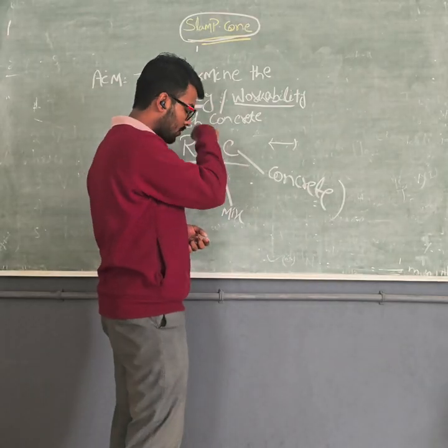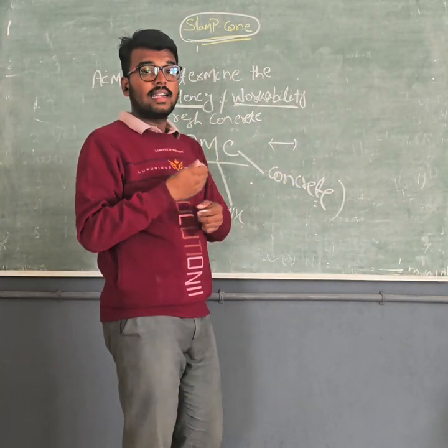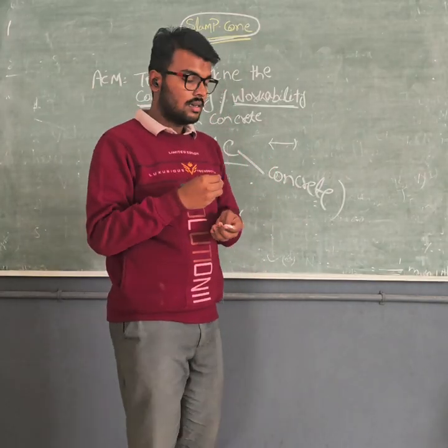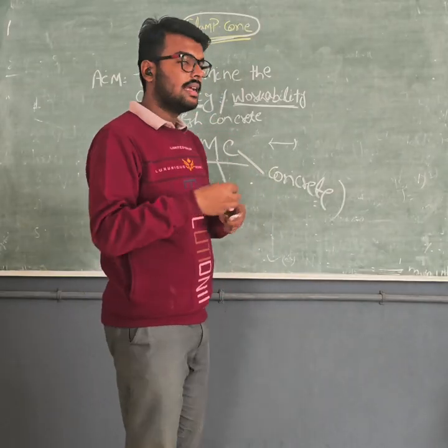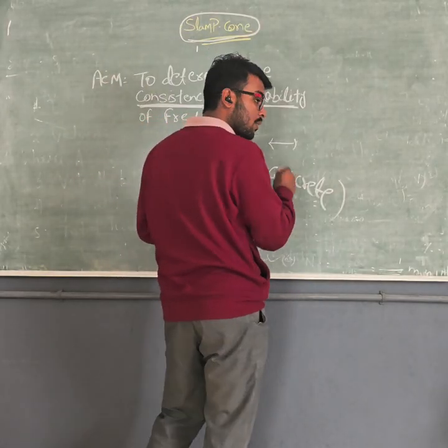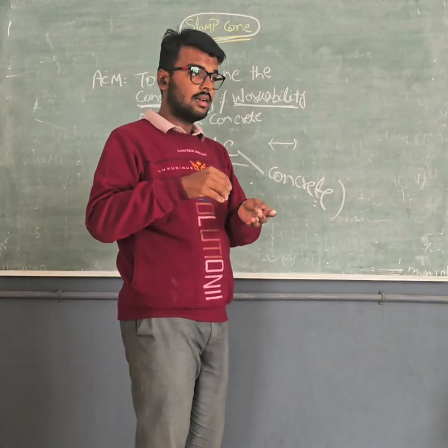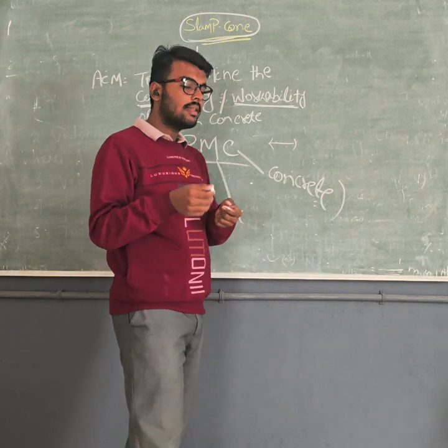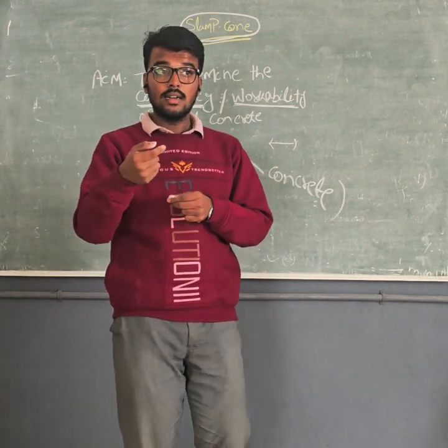So the workability begins with mixing of concrete in the plant. We mix the concrete without water in the plant. Then we transport the concrete in a van or vehicle to the site, and there we add water, considering the weather condition and casting situation of the site.